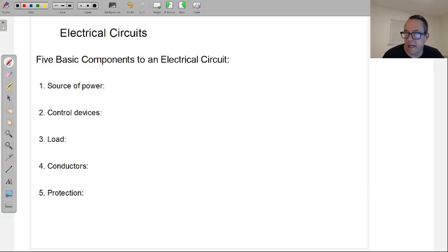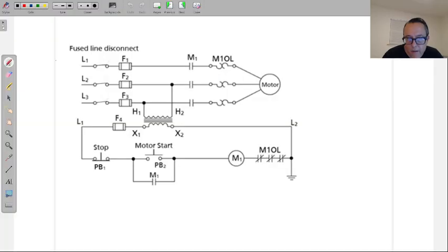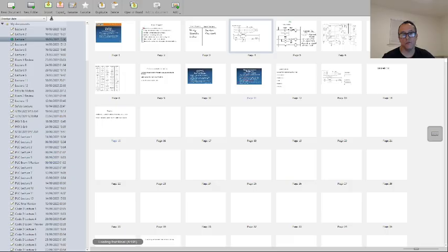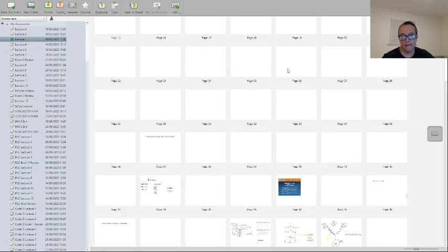All right, for example, and just to use the wiring diagram here as a reference. This is in most cases, all right? Every now and then there's a few exceptions. But in most cases, whatever voltage is coming into the system is being used to create the control power. In this case, we have a transformer, and then from there we have our control power. But as I pointed out, there could also be other things that are being used to step down the voltage, mainly what we call a power supply.